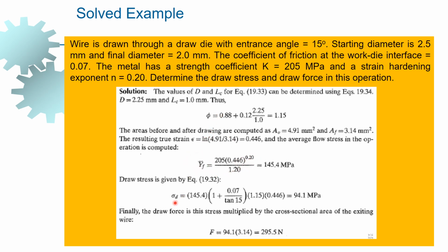After getting the flow stress, we can calculate the drawing stress using the equation. And then finally, the drawing force is the final area times the drawing stress. Using that, we can find the force required for the drawing process.